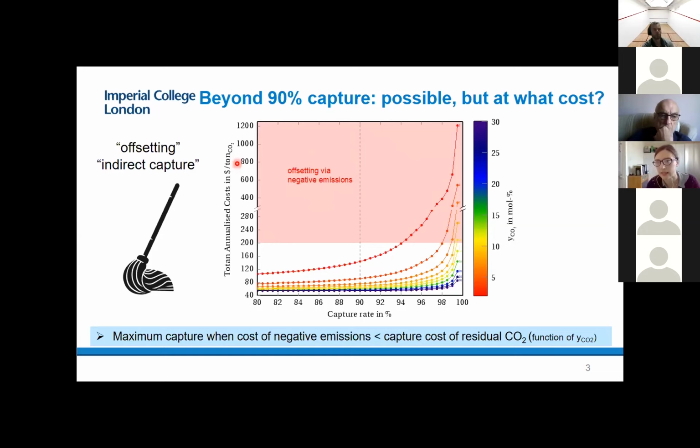I understand. So yeah, I agree with that. However, what I do is I change the operating conditions of the capture plant such that the CO2-rich stream that goes into your transport and storage network always reaches the minimum quality. In my case, that is 95% CO2 and the rest is water. And then you go into the dehumidifier and compression stages.